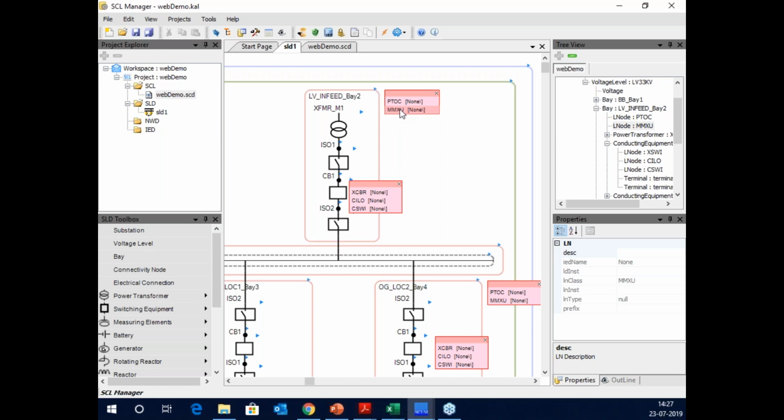There is total active power, there's reactive power, there's phase-to-phase voltages, phase-to-ground voltages, phase-to-ground currents, individual Y and delta currents and voltages. So there are dozens of data objects, and how do I specify exactly what measurements I wanted in my specification? Now this is currently a limitation.